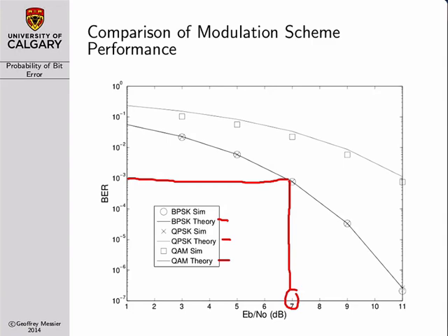And so that indicates that, first of all, our approximation or our analytical expressions are very good. And also, it highlights the point that with QPSK, you can get double the throughput for the same bit error rate when expressed in terms of EB over N naught. However, if I had shown signal-to-noise ratio in terms of energy per symbol over N naught, QPSK would require twice